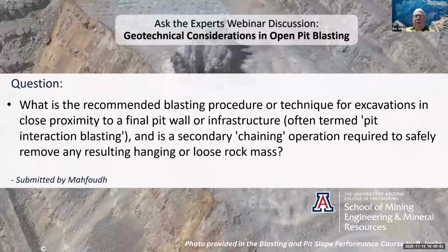I would say that's going to be a case by case basis. Depending on the geology, the lithology, structure, etc. You may want to consider pre-splitting, or if you have adverse geology, you may not be able to consider pre-splitting in close proximity to the final wall. Just that earlier example about a dip slope condition or a footwall mining condition, you may not be able to do pre-splitting.